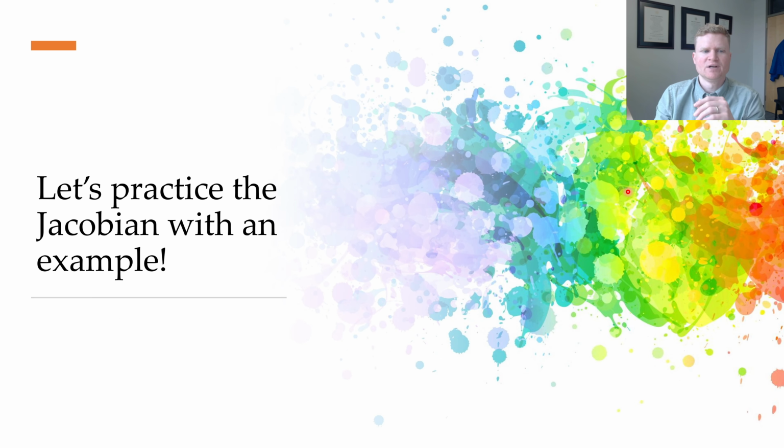So in this example, I've got a 2-link robot arm. Here's going to be the ground right here, and I've got my spatial frame that's connected to the ground. The y-axis is pointing up, the x-axis is pointing to the right, and the z-axis is coming out of the screen towards you. My robot's got 2 different joints, so it's a 2 degree of freedom serial robot arm.